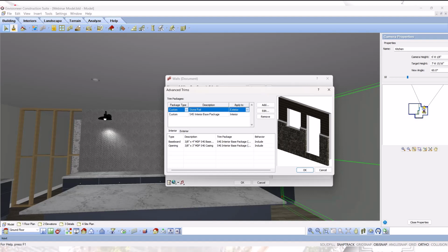Okay, so that saves a lot of time, and it also makes it more accurate as well, so that you can have that one wall not have it. It won't include it. So you want to ensure that it doesn't include it in your quantities, because if you had trim running around the entire building, but cabinets sitting in front of it, it really wouldn't be included.